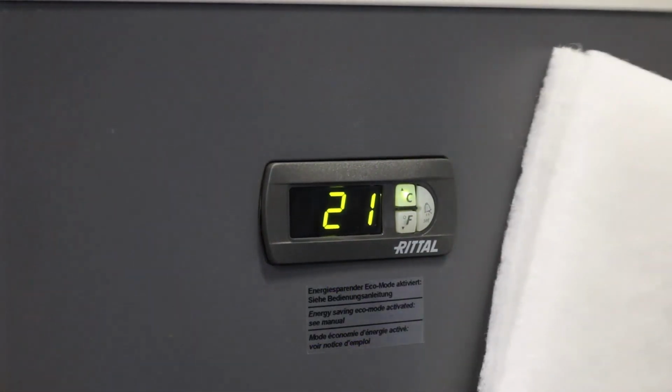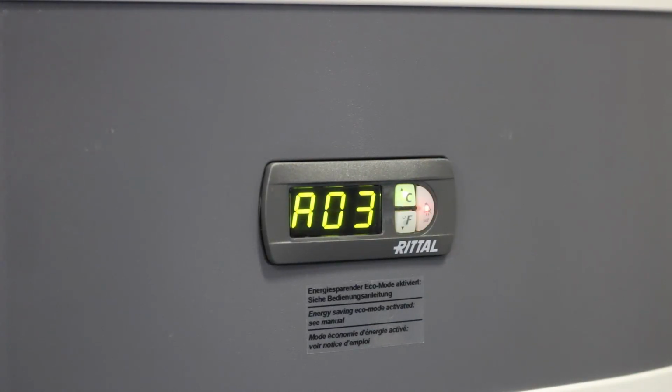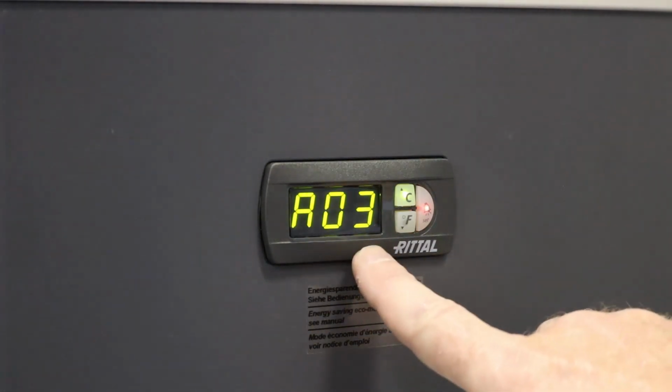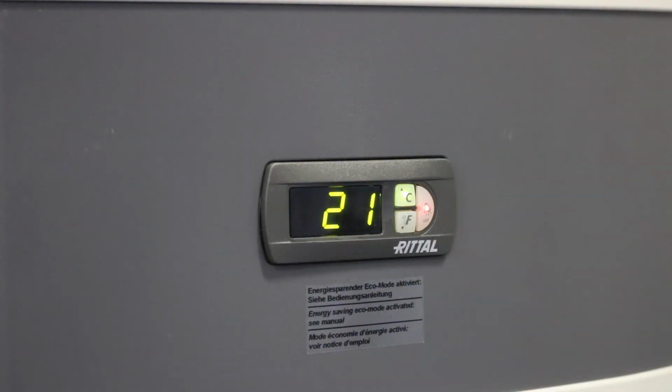What I'm going to do now is simulate the alarm for you. So I'm taking double filter material that I would usually use. I'm doubling up on that, so that creates a pretty restricted airflow. And I'm going to put that into the compartment in front of the condenser fan. And you can see what's happened here. Now there's been a time lapse of about 1 minute, but you can see now that I get a code A03, and that's flashing. A03 is my code for filter monitoring alarm. You can also see to the right a little red dot or a light that's on my set button. So it's alternating the internal temperature plus my alarm code.